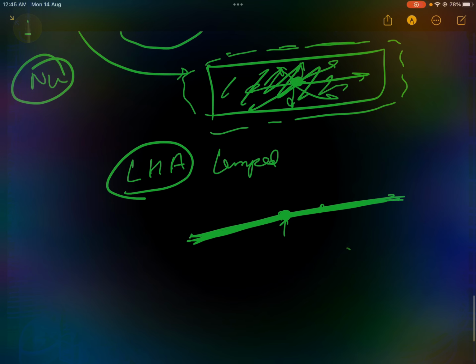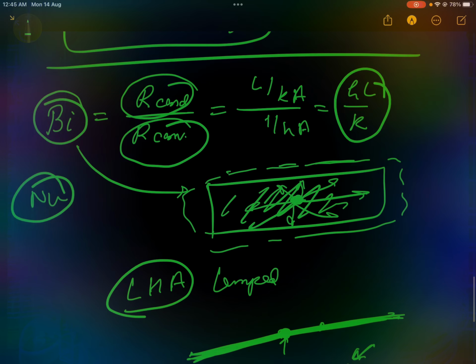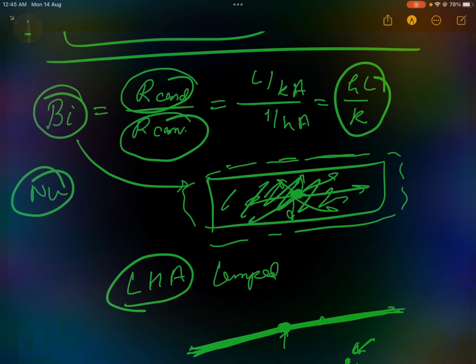Or let's say we have a thermocouple in which we use very tiny balls. We don't want the heat to take time to distribute itself throughout the material, because we want to measure the outside temperature. So what I want to say is that the Biot number focuses on the heat transfer rate within the material, so that it can distribute the heat uniformly within the material.